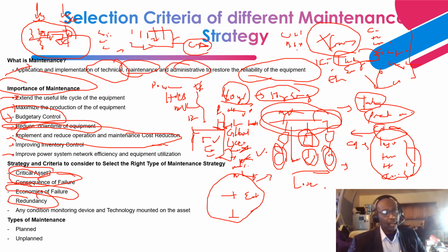Here I have redundancy in this configuration. If I have to take this transformer out of service, then I'll have an n-1 configuration. That is removing one of these power transformers out of service and transferring all the bus load onto this one transformer and closing the tiebreaker.